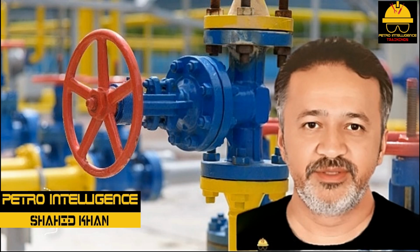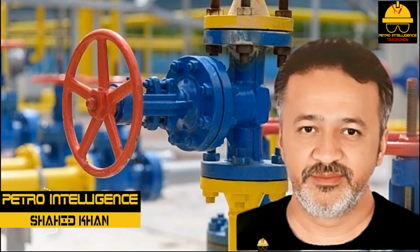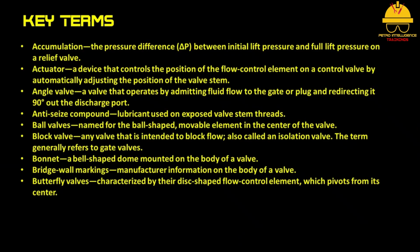Before starting the course, let us have a look at key terms. Accumulation is the pressure difference, delta P, between initial lift pressure and full lift pressure on a relief valve. Actuator is a device that controls the position of the flow control element on a control valve by automatically adjusting the position of the valve stem. Angle valve is a valve that operates by admitting fluid flow to the gate or plug and redirecting it 90 degrees out the discharge port.